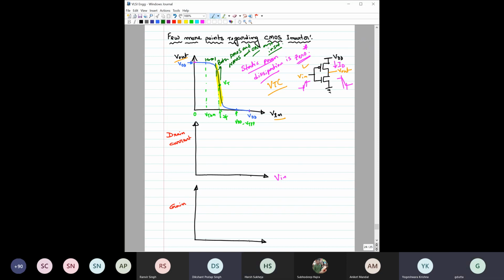No, sir. Why no? Yes, but lower. See, because only for this region the NMOS is off, right? Only for this region the PMOS is off, right? Other than this region, here completely NMOS, PMOS is on, right? Again, outside from here till this point, in all regions NMOS is on.